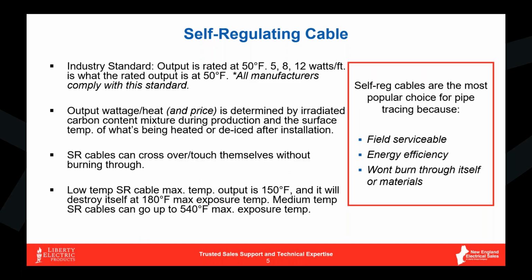What happens with self-regulating cables is they actually work off of a contraction and expansion at a molecular level going on inside of that cable. The driver of that is a material called carbon black or irradiated carbon. We're going to see that in another slide here. But basically the content of that cable, how much of it is comprised of that material, is also going to determine how many watts per foot this thing's going to output.